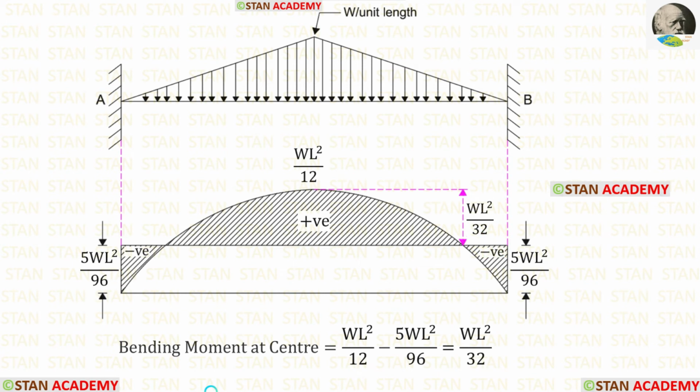In this bending moment diagram, there are 2 points of contraflexure, one on the left side and one on the right side. We have to find any one of the distances because both of them are lying at the same distance from the ends. Let us find the distance of point of contraflexure on the left. For that we have to make one section.